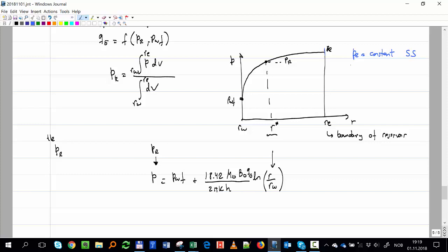And then we have if Q is 0 at RE, that means that it's isolated, like if I have a fault, there is no fluid flowing through that boundary. If the pressure is constant, it's like if I have water injection, fluid is being pushed towards that boundary to keep the pressure constant. If not, then the rate is 0, and how do I call that regime?